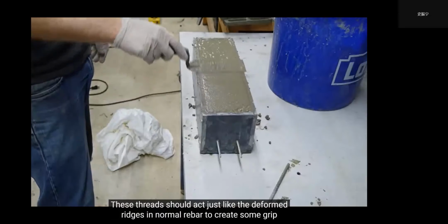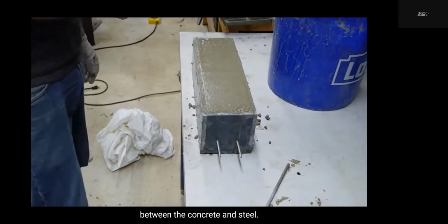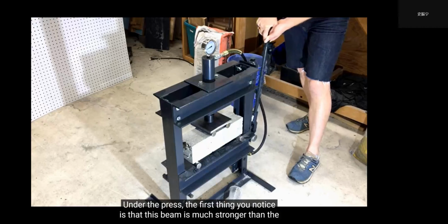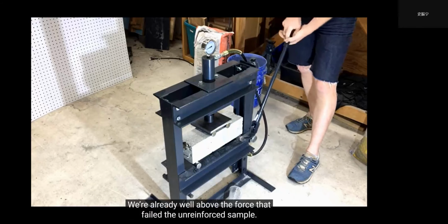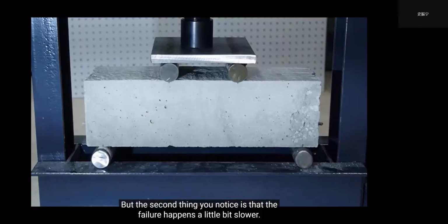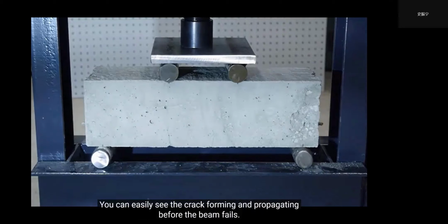These threads should act just like the deformed ridges in normal rebar to create some grip between the concrete and steel. Under the press, the first thing you notice is that this beam is much stronger than the previous one. We're already well above the force that failed the unreinforced sample. But the second thing you notice is that the failure happens a little bit slower. You can easily see the crack forming and propagating before the beam fails.